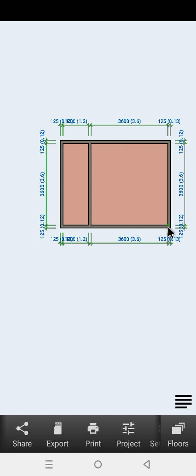It is best to first know the size of the block that will be used on the site, so that you won't use 6 inches blocks, for example, only to get to the site and find out that the blocks to be used are 9 inches. By then your calculation will get mixed up. I don't know if you understand.